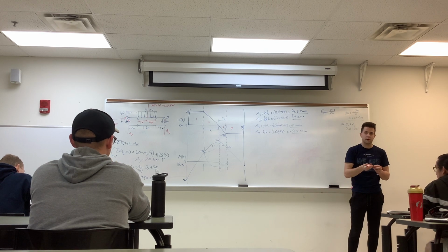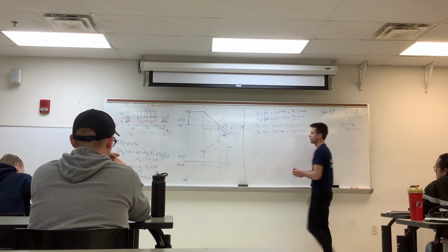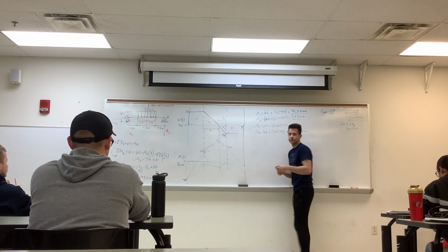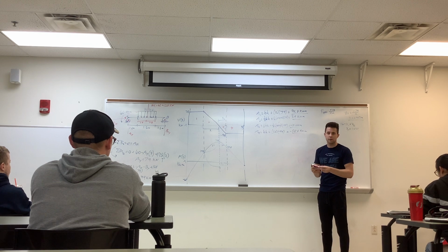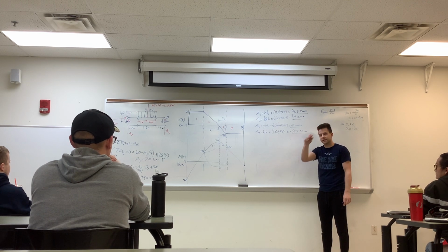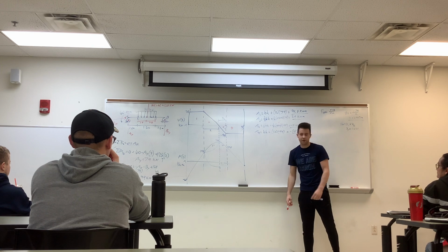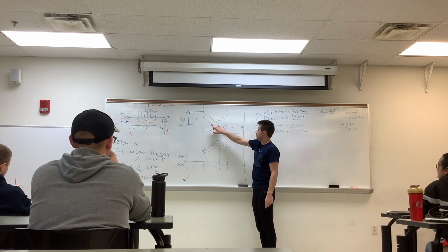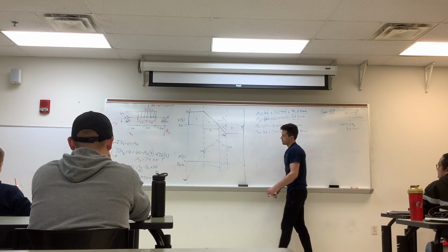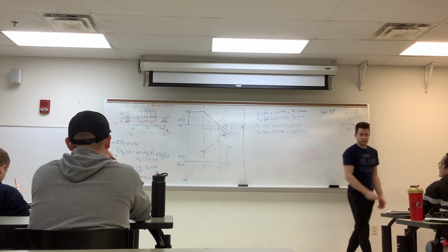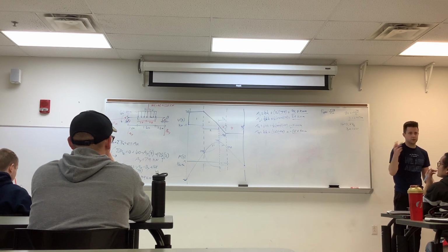I just wanted to make sure when it crosses the plane on the shear one, you'll always have a top out in the moment, right? Like that's kind of the local maximum. The slope will always be 0. It could be decreasing to a spot, then going back up if the loading is going upward. But in the case of this, which I don't think I would give you anything that radical, it'll almost always be the slope at 0. That's the location.